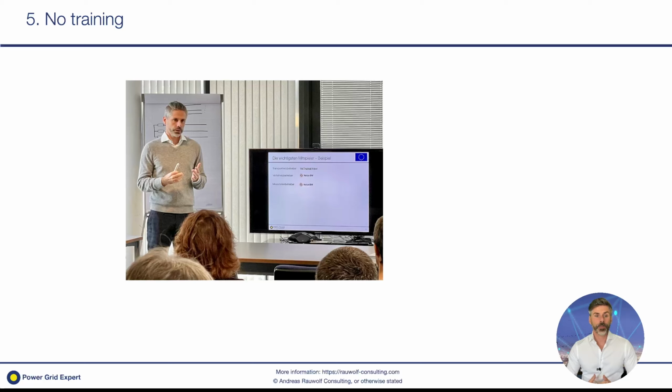Last but not least, engage your people. Train the guys who have to use those devices. They have to be confident in how to operate the fault indicator, the protection relay under normal operation conditions. They have to absolutely know how the device indicates in case of a fault, how to follow the directional indications. If you're not confident in that, you're stressed, and again, stress in those situations is a bad thing, so we want to prevent it.